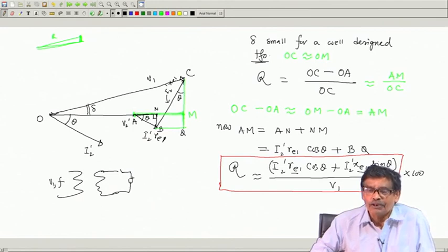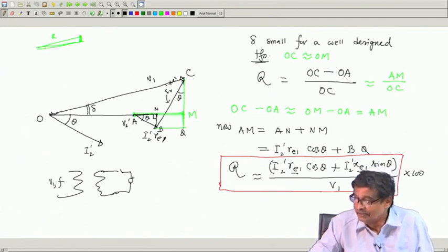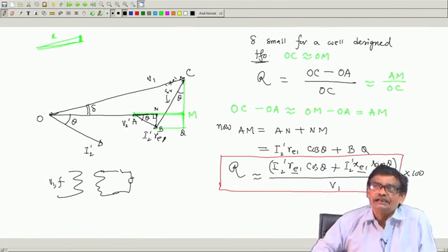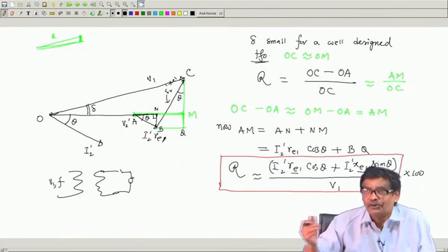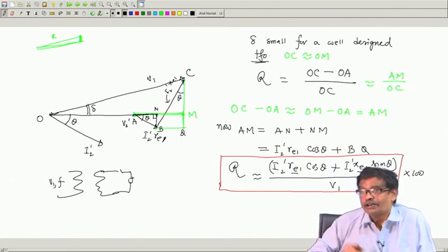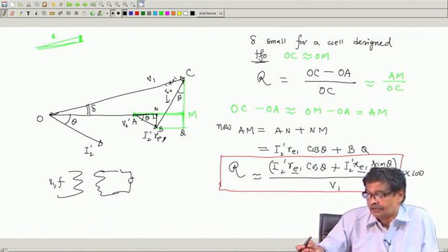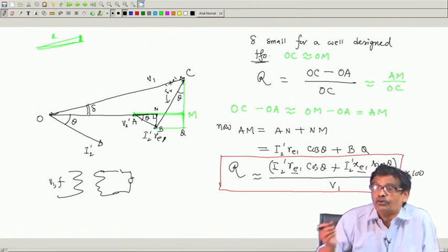Okay? Because open circuit and short circuit tests are very simple tests. I will carry them out, find out these values, then tell me any load current the transformer is delivering, of course up to rated current, and at what power factor. You give me these two pieces of information, and I will be able to give you the value of regulation, how much voltage will drop.